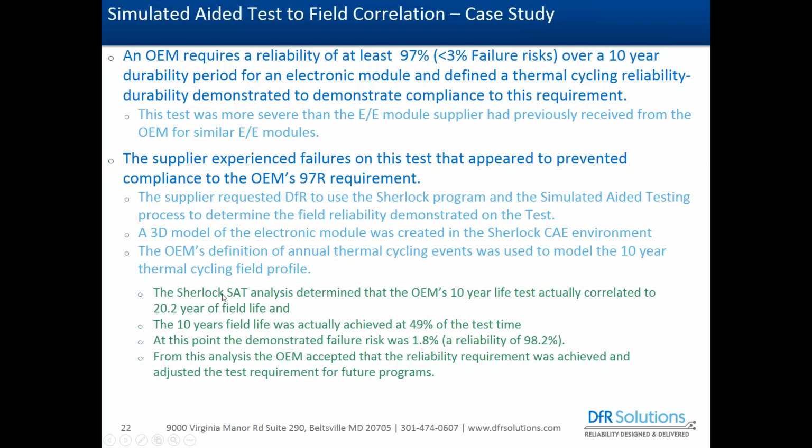And when this was all done, we determined that the OEM's 10-year life test actually correlated to 20.2 years of field life, and that the 10-year field life was actually achieved at 49% of the time into the test. And at this point, the demonstrated field risk was only 1.8%, which meant the reliability was 98.2%, which meant that it did meet their requirement of less than 3% failure risk.